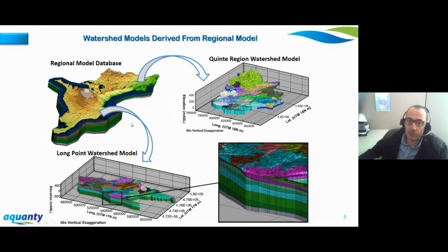For the regional model, we carried Strahler order 3 and larger, just to keep the node counts in limit, so the model will run quick enough. But for the watershed scale model, we increased to Strahler order 2 and above, for higher resolution. In later slides, I will show a side-by-side comparison of these mesh scales.